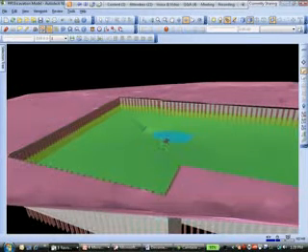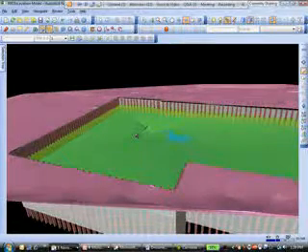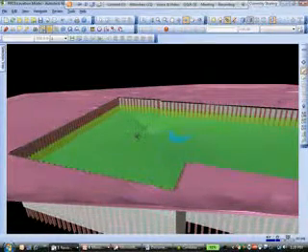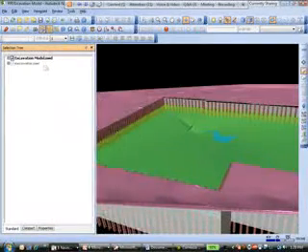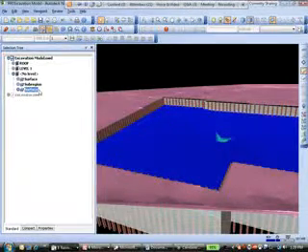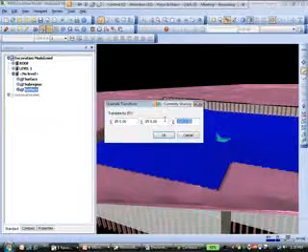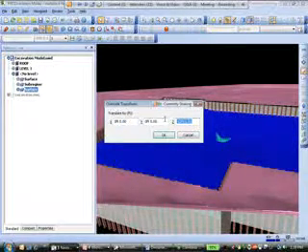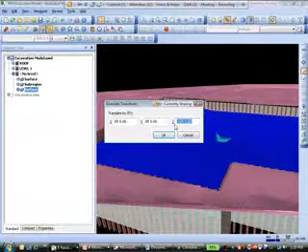With this information, now I can start planning what this is going to look like, how much equipment is going to be required to excavate this, and it becomes more of a site logistics planning tool. So if I go back to the selection tree, one of the things I'm able to do is select the surface, and then using the override transform, I can move this up and down and start to figure out approximately the kind of equipment I'm going to need in here.